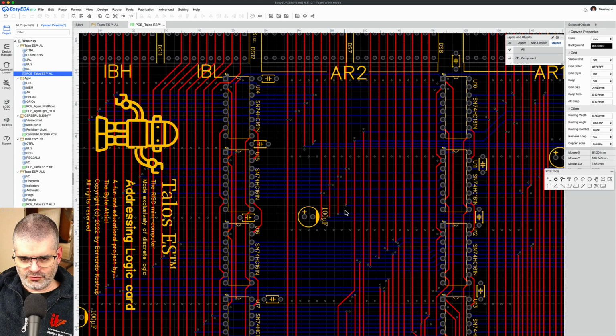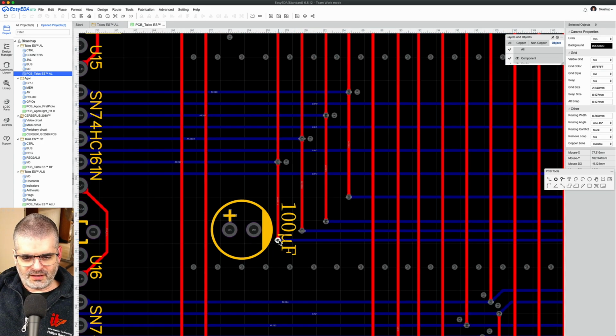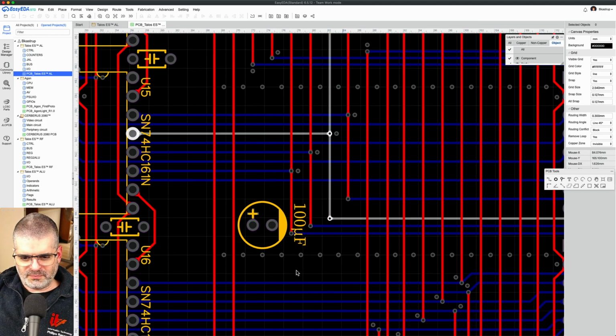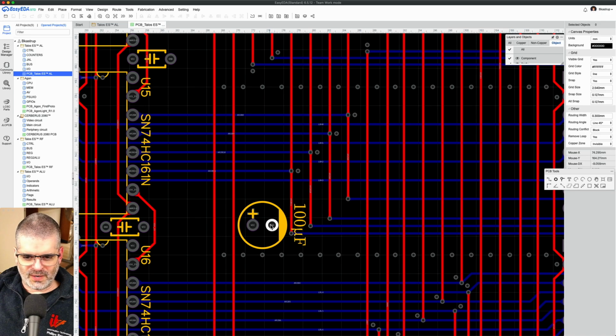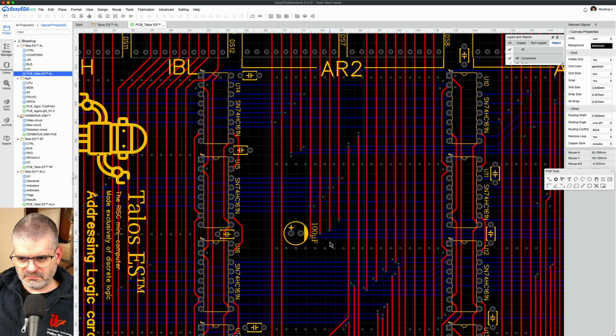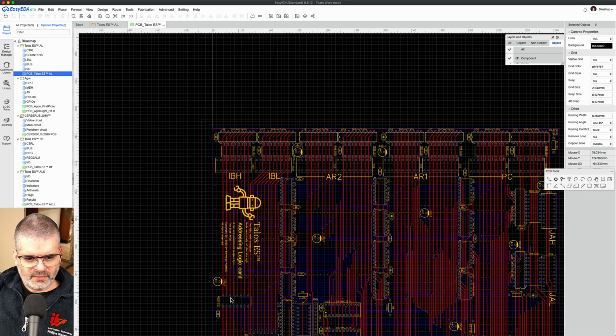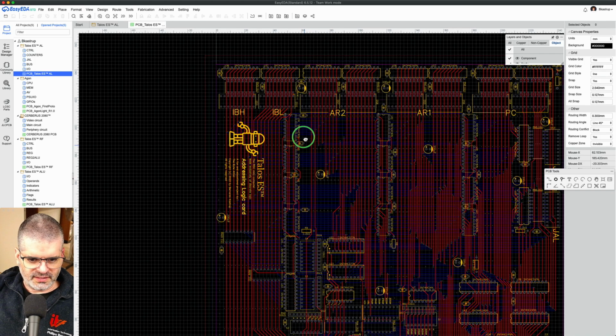But it's an error. I didn't avoid putting the return path vias here for any good reason at all. I just forgot. And I'm not going to change this because I don't want to put online Gerber files for a board that isn't exactly the board I made and tested myself. And I'm not going to make another board and test myself just because of these missing return path vias, especially because we have the transfer vias there and we have a big ground pin very close by, which will work as a return path via, so to say. So this is okay. And there isn't much more to comment except some electrical details.